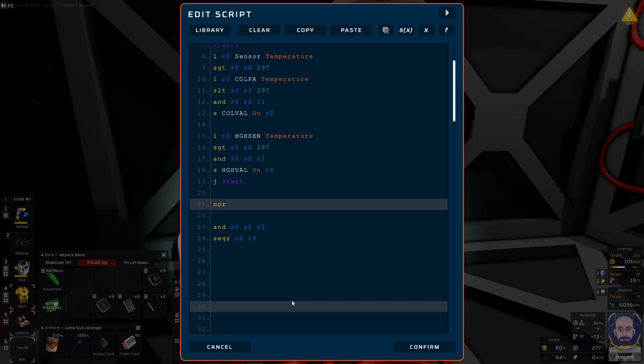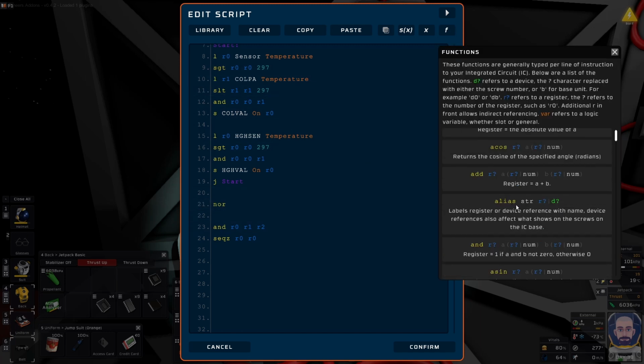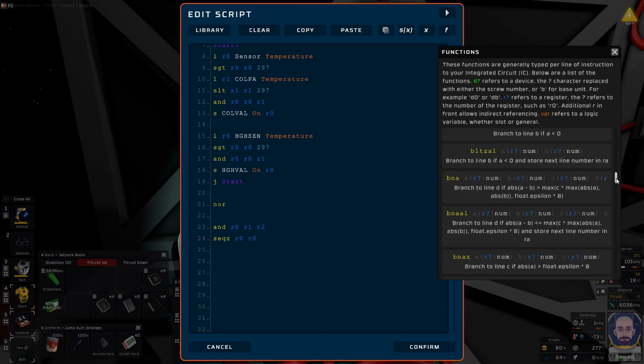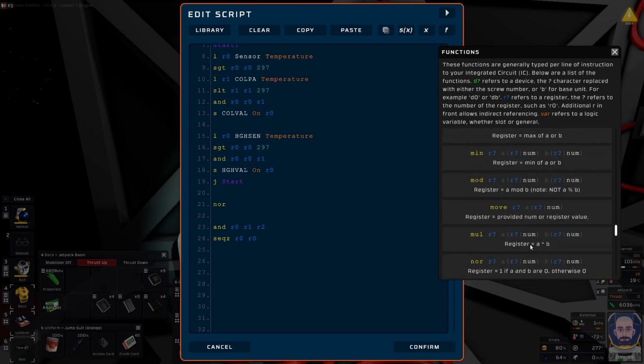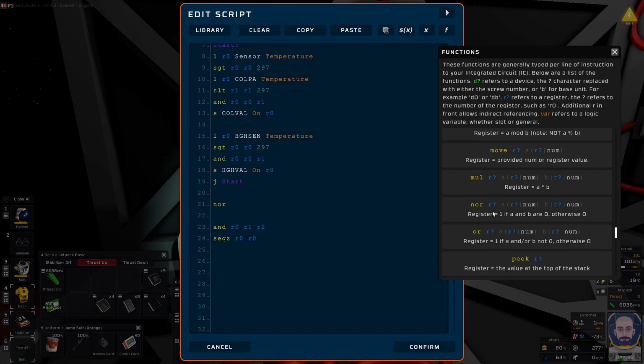Apologies for my jump edit there because I have lost a little bit of footage, so I'll just do it again quickly. This is the NOR that we saw, the not OR. So same as OR, but with the not in front of it. So if we go down here, you will see that the registry value that you set at the beginning is 1 if A and B, the other two registers, are both 0. Otherwise, it'll be 0. And we don't have a NAND, a not and.